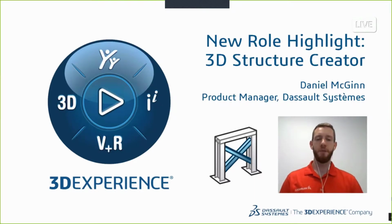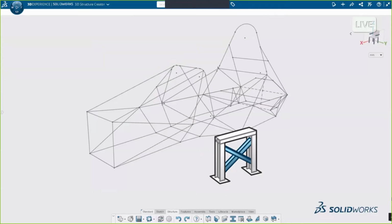In the spirit of Le Mans and the theme for this year's SLUGME event, I'll show off some functionality in 3D Structure Creator by designing a race car chassis. I'll start my chassis design with a skeleton sketch. I can freely select sketch segments in the graphics area to use as a reference for creating structure members. I can quickly access the structure member command from the pop-up context menu.